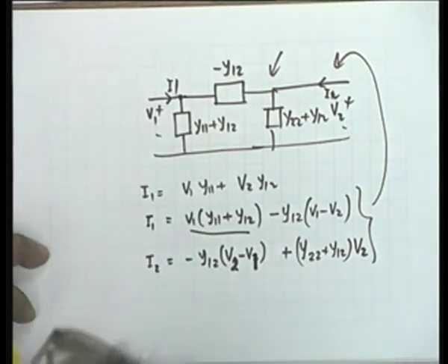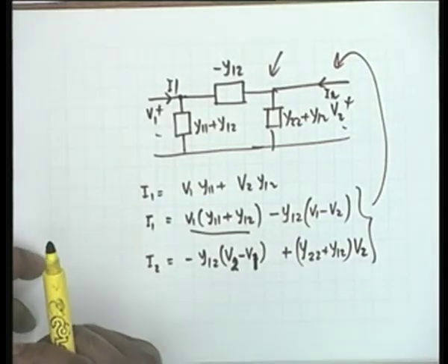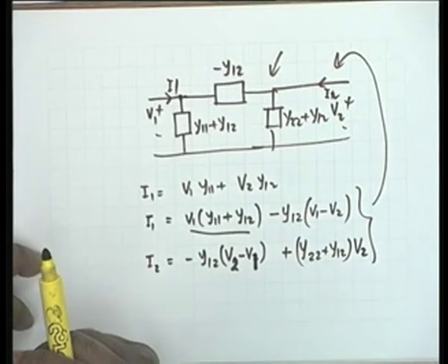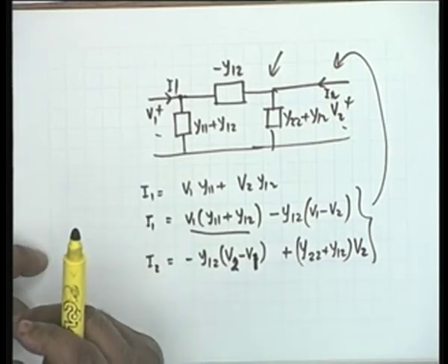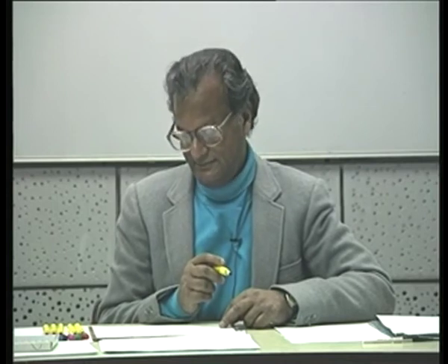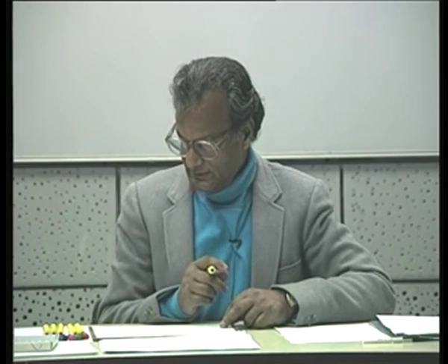The equivalent circuit would be a physical equivalent circuit if the general two port is 3 terminal. It is a mathematical equivalent circuit if the general two port is 4 terminal. Alright? Excuse me, sir. Here we are getting minus Y12 as one of the admittances.